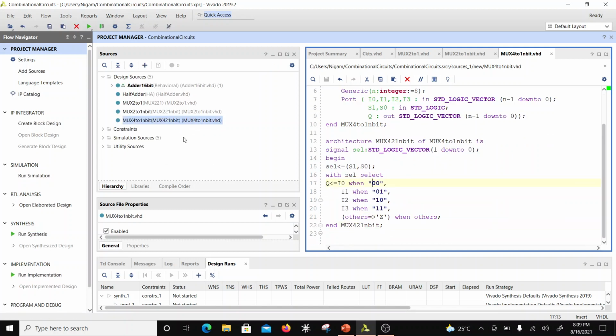So you can design any kind of mux, but the question is, what's the approach when it is 4:1, 8:1, 16:1, 32:1? When this keeps on increasing, what's a good way of doing this? The good way is using something called tri-state buffers.